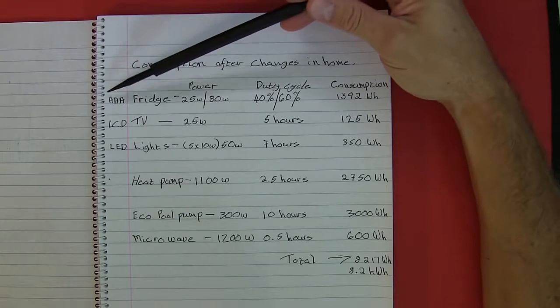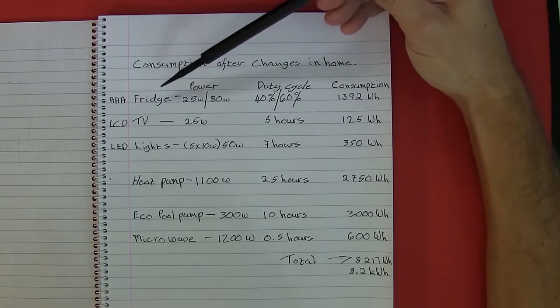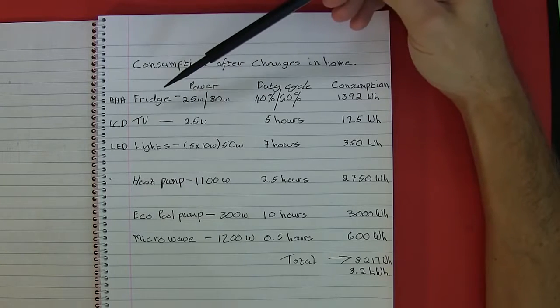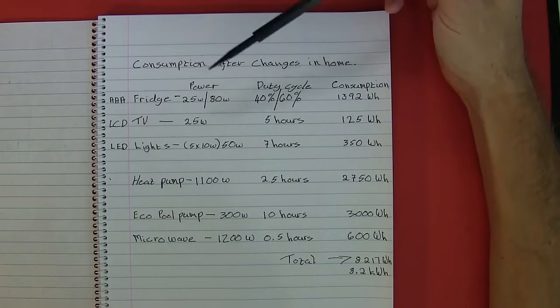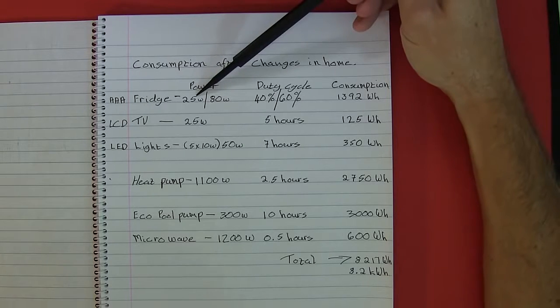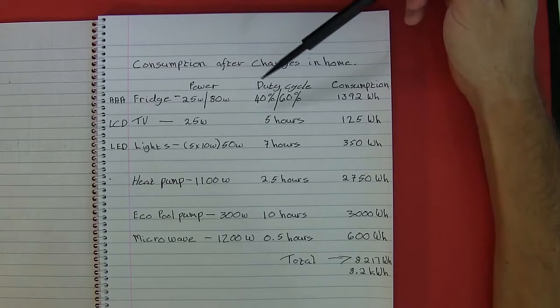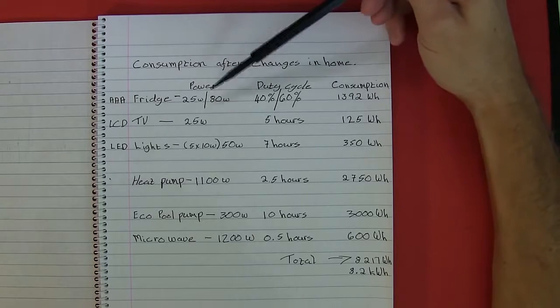They have a rating to say how efficient they are, AA or AAA, and that means that they have motors that run more efficiently. They also have better insulation, which means they don't have to switch on as frequently. So you've got a double saving there. The low running power could be dropped to 25 watts. Its running power, when it's actually circulating refrigerant with a motor, could be dropped as low as 80 watts. And then the duty cycle can be reduced because the insulation is better on a fridge like this, so it's kept colder.